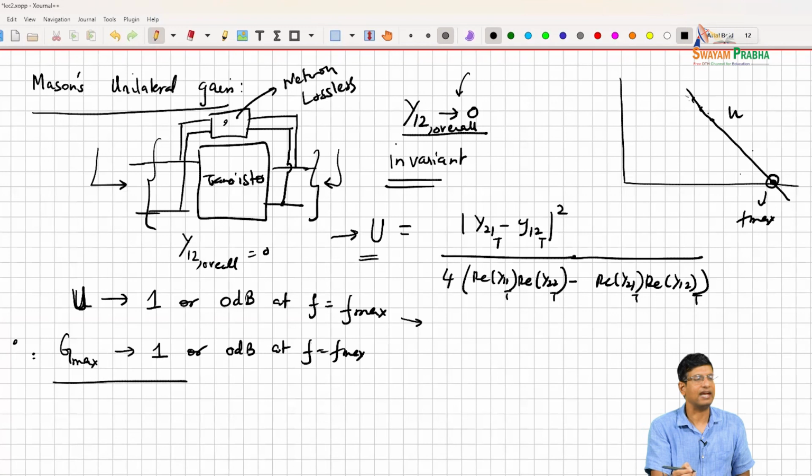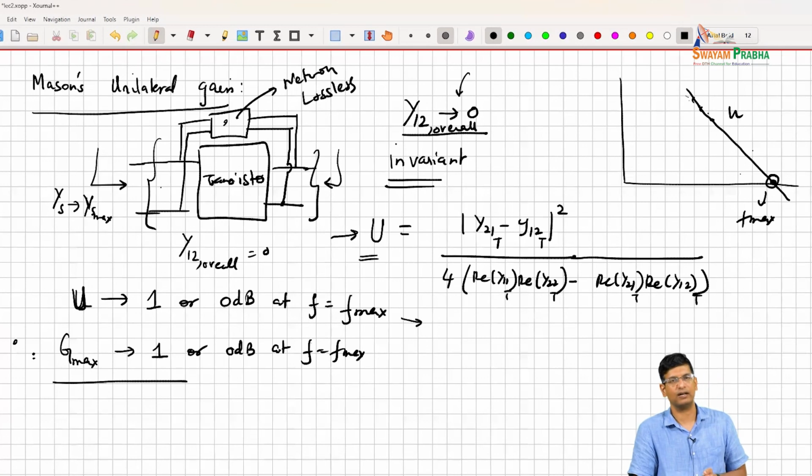So then it's very easy for you to design, because you can just figure out the input impedance that you see here, and then find the matching network to go from Ys to Ys mats, and similarly, here you can go from ZL to ZL mats. You don't need to design both of them together and solve those equations, right? So this is again very useful if you're designing unilateral amplifiers.